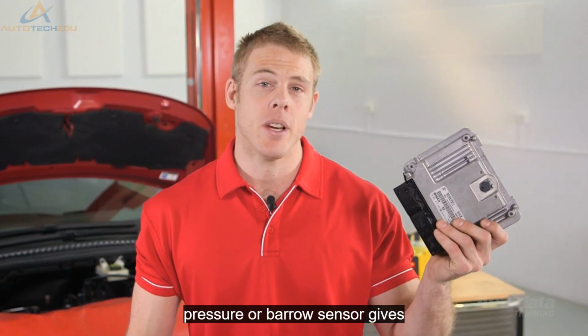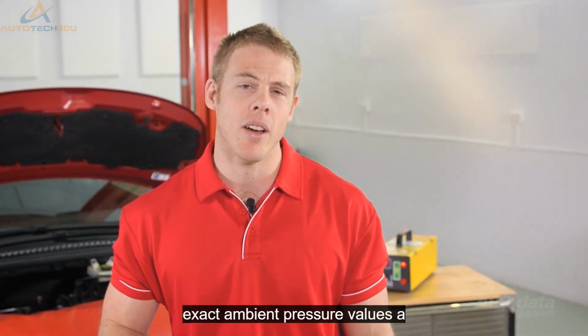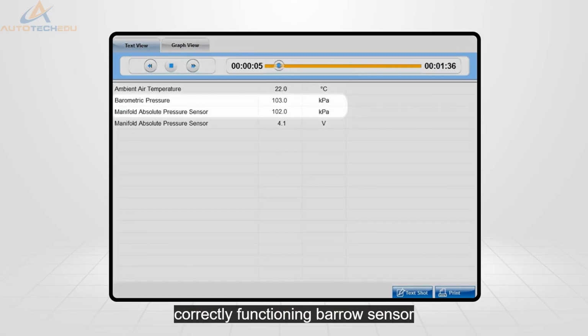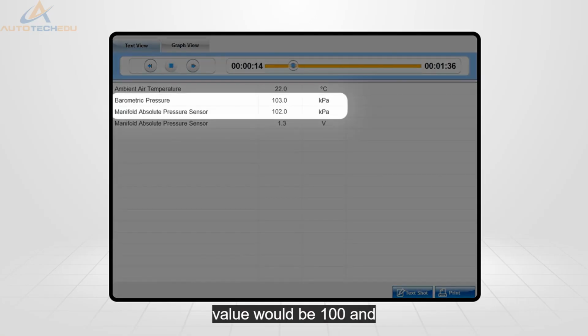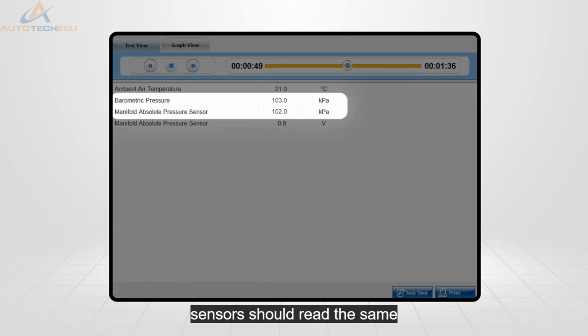The barometric pressure, or baro sensor, gives the ECM the exact ambient pressure values. A correctly functioning baro sensor value would be 103 kPa at sea level. Allowances will need to be made depending on your location. The MAP and baro sensors should read the same with the engine off and ignition on.